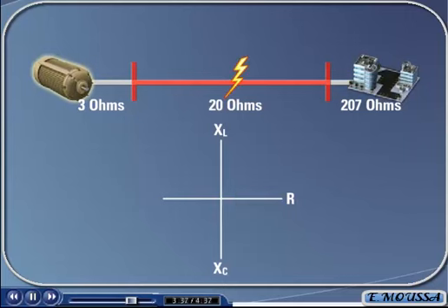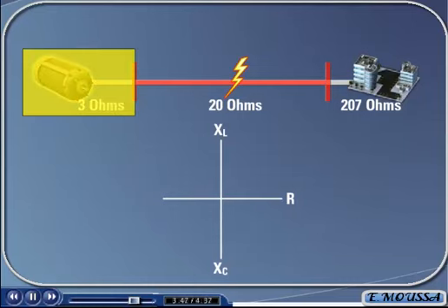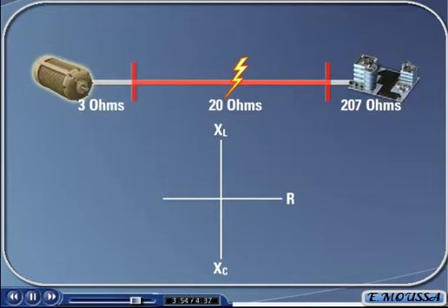If a fault to the ground were to now occur at the midpoint on the transmission line, all of the impedances after the point of fault would no longer be part of the power system. The impedance of the system would now only be the impedance of the source plus the impedance of the part of the transmission line before the fault. Since the power system impedance is no longer mostly resistive because the only impedance is now the transmission line, which is mostly inductive, the plotting of the measured impedance on the RX diagram will be very close to the y-axis.